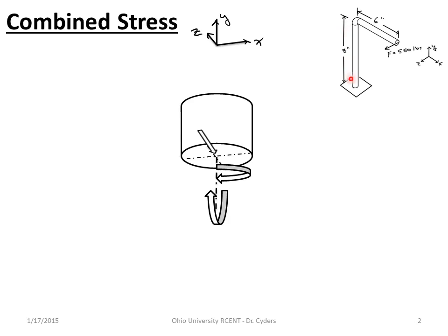The bending moment about y is going to be maximum here at this end. In this part of the beam, that's actually going to be a torsion, and then I'm going to have that same torsion all the way down the cross section. So we've got a transverse shear that's constant along the 8-inch section. I've got a torsion that's constant along the axis of the 8-inch section. And I've got then a bending moment that is maximum here where it's mounted.